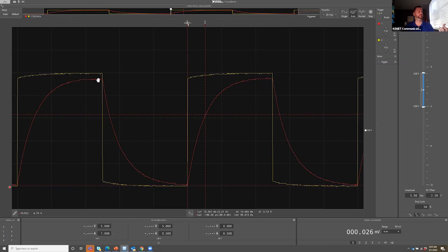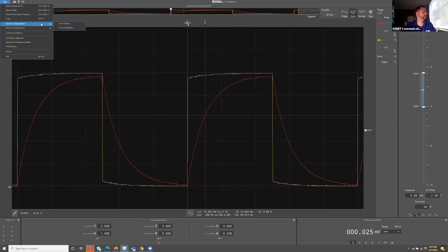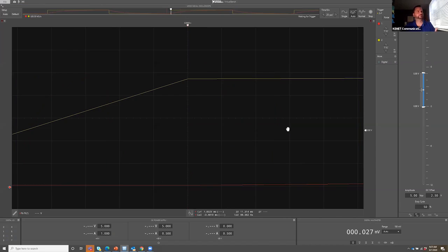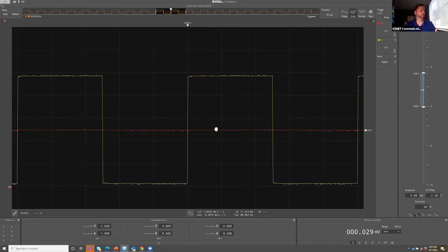That's definitely true. So what I'm going to do now is I'll change the setup here to go at a faster frequency. Right now, I'm only going at 10 hertz, so rather slow. So slow enough that this capacitor has enough time to charge almost fully and discharge with every cycle of this waveform. But when I go at a high enough frequency that the capacitor doesn't really have time to even charge or discharge or respond, that's where you get into that low impedance scenario. And the input now is coming in at 10 kilohertz, so 1,000 times faster.